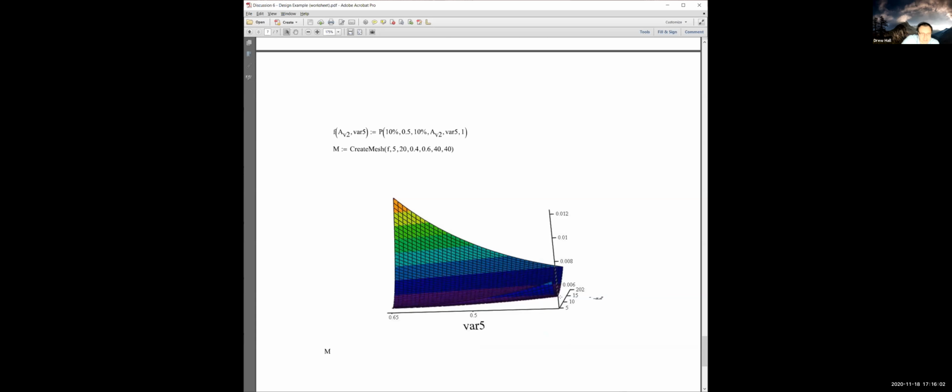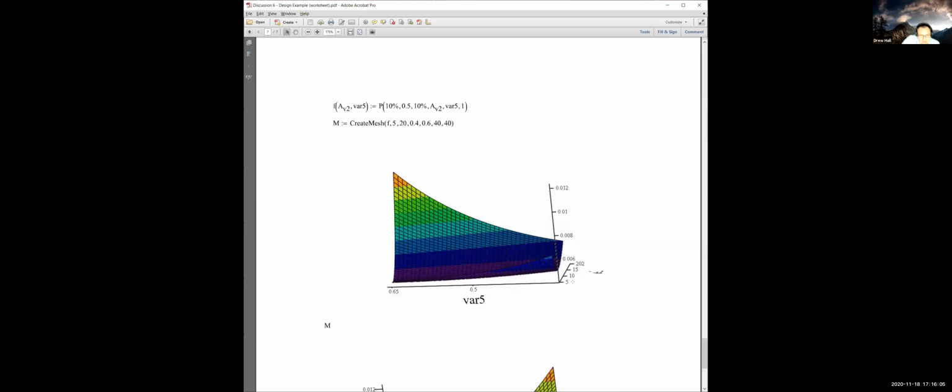And so what is this plot showing us? This plot is showing us a couple of things. On this axis here is the gain, right? The z-axis is the power. And so if I try to put this up with a whole bunch of gain, and I try to move the time constant over here, you can see that we end up in this portion of the design where it takes a bunch of power. Basically, I'm shoving a whole bunch of current down M2 in order to make it have a lot of gain, but I'm also having to deal with the Miller multiplication of CGD.